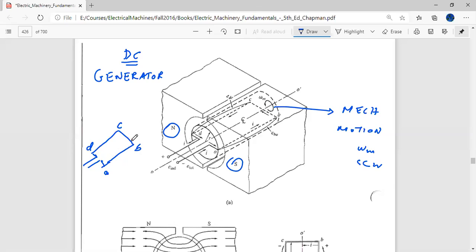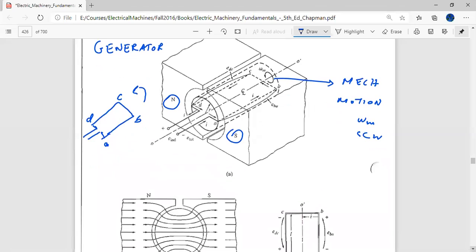Okay, so we are going to consider what is the impact of the motion of this single loop of wire when it rotates in an anti-clockwise direction inside these magnetic poles. And one key thing to notice is that the poles have curved surfaces, or rather circular surfaces. So one semicircle is formed by the North Pole and another semicircle is formed by the South Pole. When the pole pieces are curved, it has a very natural effect, and the natural effect is